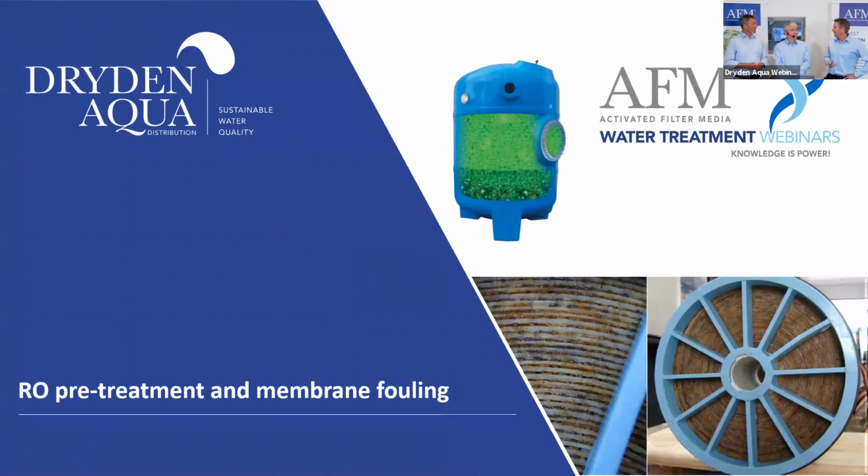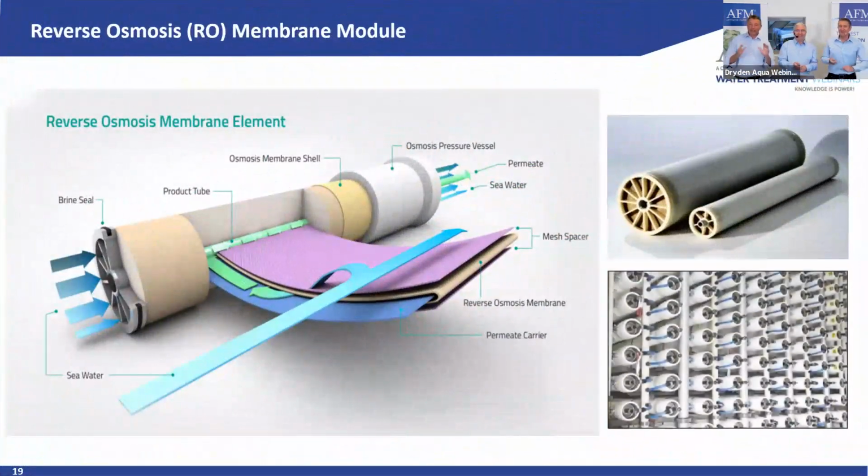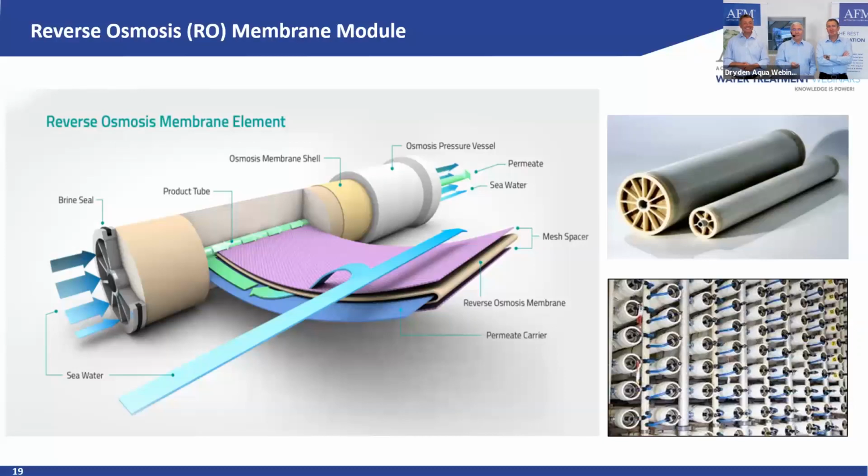So now you open your part. Okay. Everybody fights here. Thank you. So let's start before we go into the different fouling properties, or let's say fouling potentials, we look into the membrane module. Here we have a membrane module. Most of you are familiar with this one here. That's the membrane mesh spacer. That's providing the gap between the membranes. You can see in light brownish here, that's the membrane. You have about 25 leaves in a membrane module, and you have the same amount of sheets here. That means this is the biggest area susceptible to fouling, and where we're talking about in the next couple of minutes.